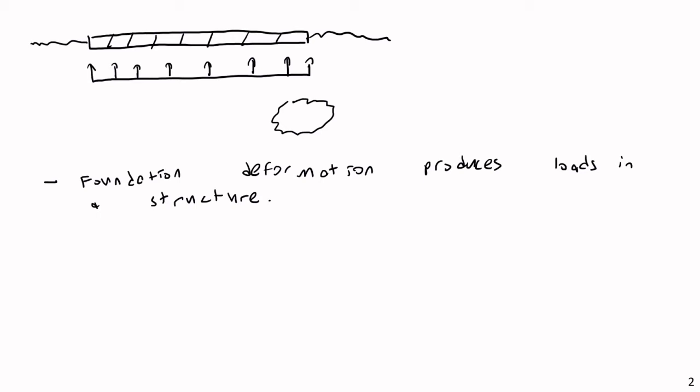Just like there's no such thing as a structure that can resist any load with zero deformation, no foundation is perfect either. Any foundation made of real materials is going to deform under some load. So when I say I want a foundation that can resist these loads, the geotech engineer might come back and say, okay, I have done this, but here is the actual way this foundation will physically perform. Yes, this foundation is strong enough to resist the loads that you have given me, but it is going to deform this much. So make sure the rest of the structure won't be harmed by those deformations.